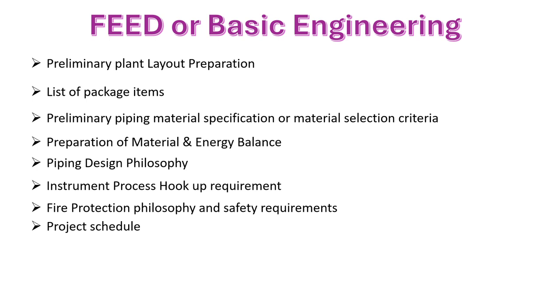Okay, how the project proceeds, how much time it takes for a particular activity, activity bifurcations, and its milestones need to be defined during this phase. How long does it take for the civil activity, then the mechanical erection and piping, then hydro testing, then the software like SAT, instrumentation testing, hot loop or cold trial, hot trial prior to startup. That needs to be taken care of in the project schedule.